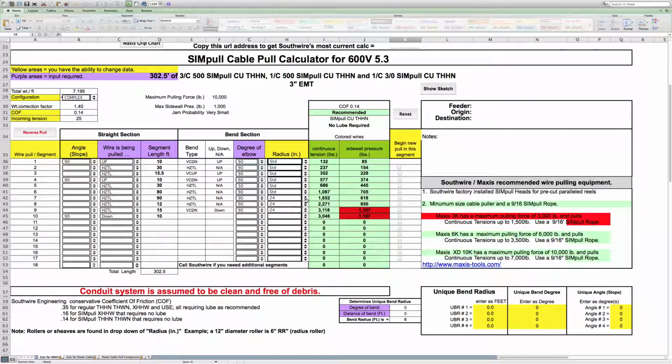So then I'll pick the next most likely sweep I've got, which would be 36 inches, and make them all 36 inches. That way I don't have to worry about putting them in the wrong place. If the last three elbows are all 36 inches, when I'm green, I can pull all the way through from one piece of equipment to the next with all these 90-degree elbows. I do have to have a junction box after that fourth 90, after 360 degrees, but I want to put it in pull-through fashion. I don't want to use my pull box as a 90-degree elbow.